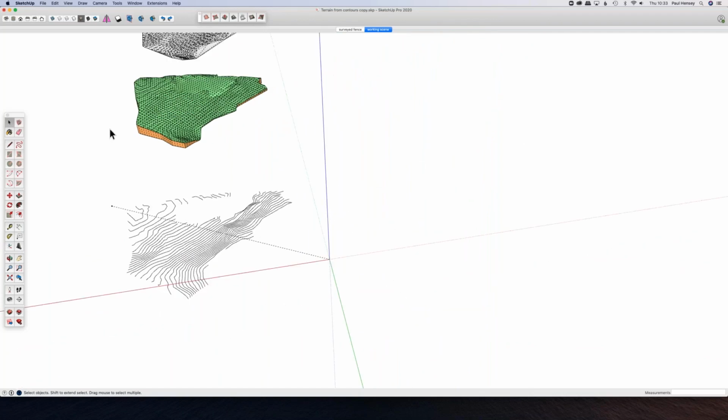So if I now select that point and then run the extension, try again, extension, Elevate Contours. It's asking me what the increments of my contours are going to be. So I'm going to say, I don't know, 0.5. Well, let's go with 0.5 meters and say OK.